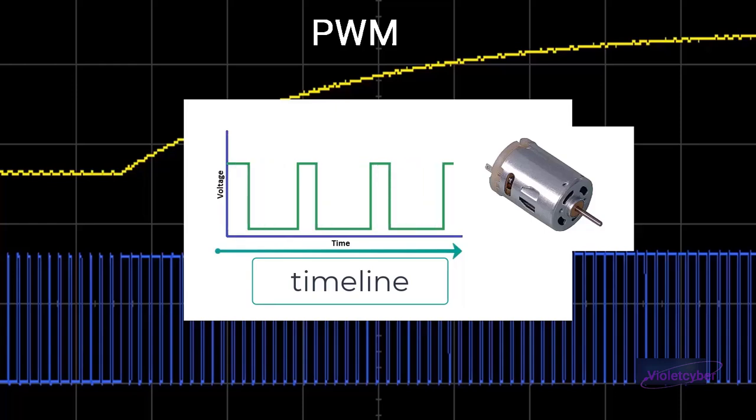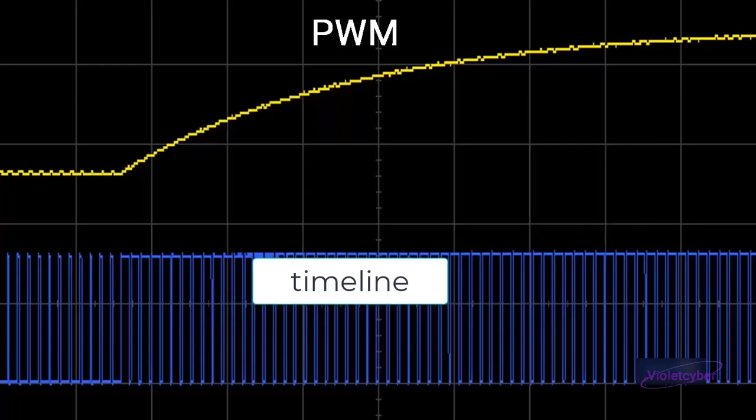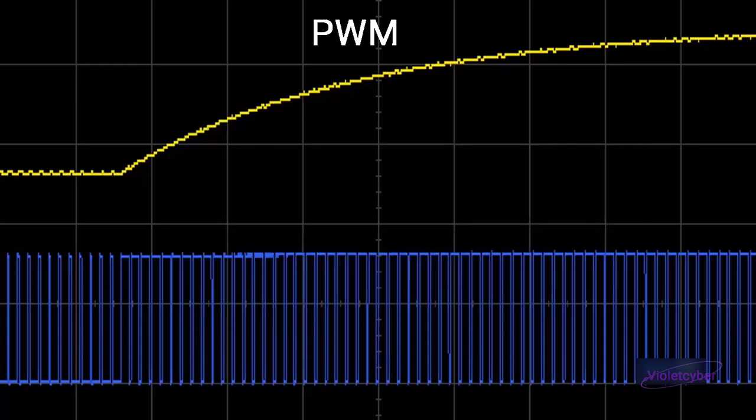The advantage of using PWM with microcontrollers is that based on various parameters, we can program the PWM pulse signal to change its state. For example, the robot moves at a certain speed, and when it approaches an obstacle, it reduces its speed, which is the simplest example. A robot moves quickly and at the same time reduces or increases its speed again. All such functions and control over the motor are possible with PWM pulses.